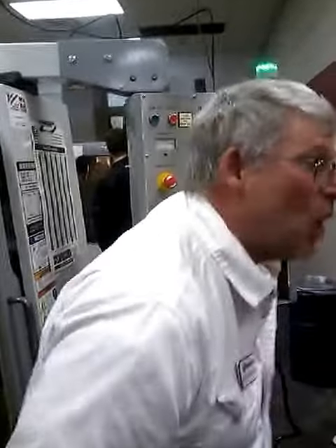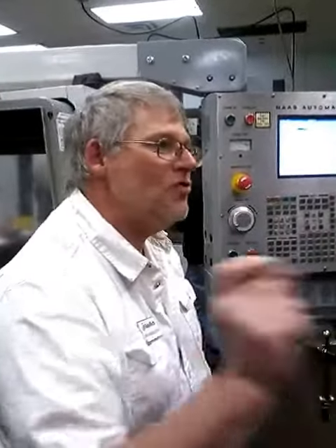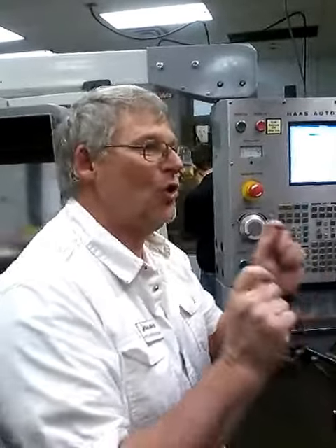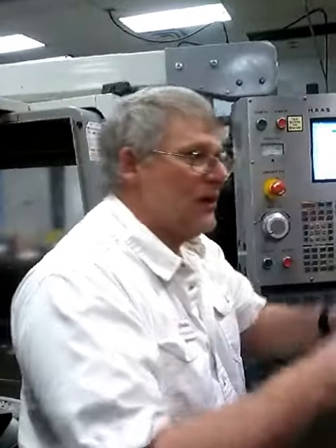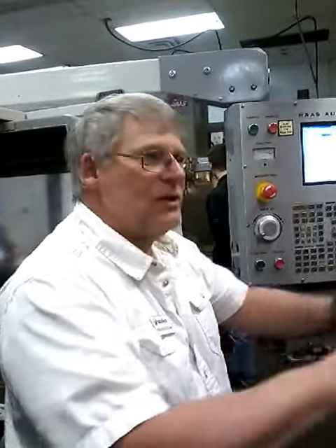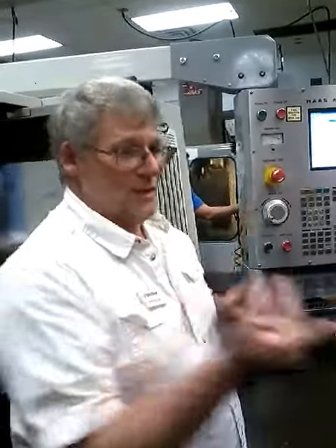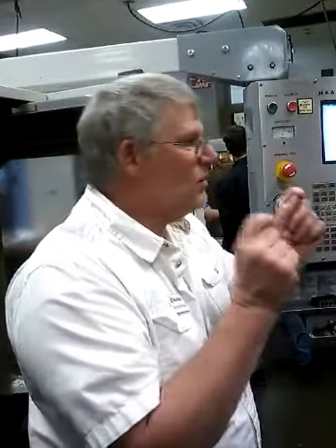So is the table moving or the machine? It doesn't matter, because we always view movement as if the tool were moving. When we start programming and moving a machine around, I don't care what function is actually moving. I want you to think I'm moving the tool. That's always going to work for you, because machine manufacturers do all kinds of weird, funky things. This doesn't change. If you always view movement as if the tool were moving, you'll get along with any machine. Cool?